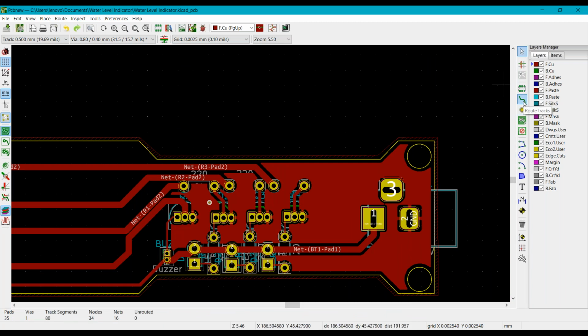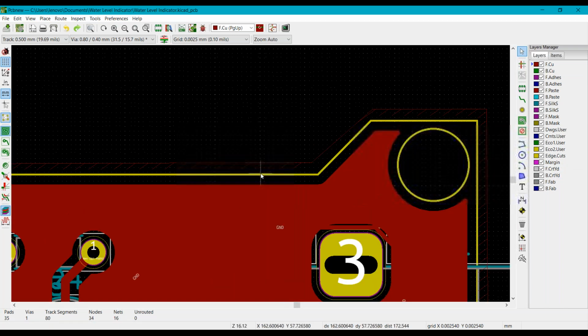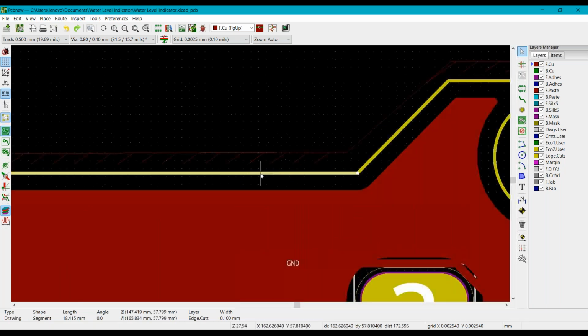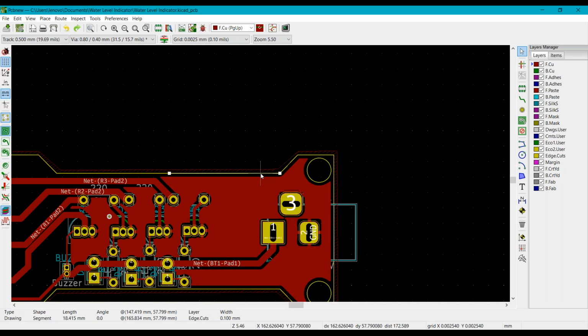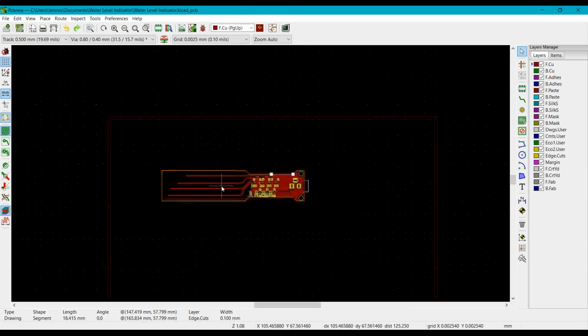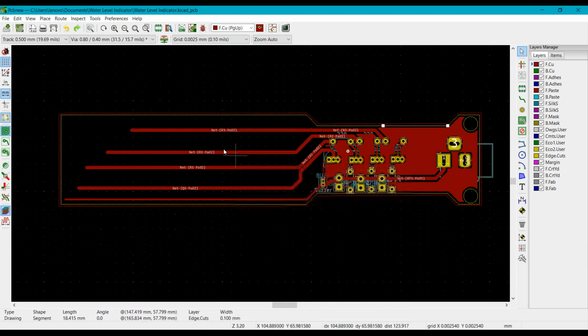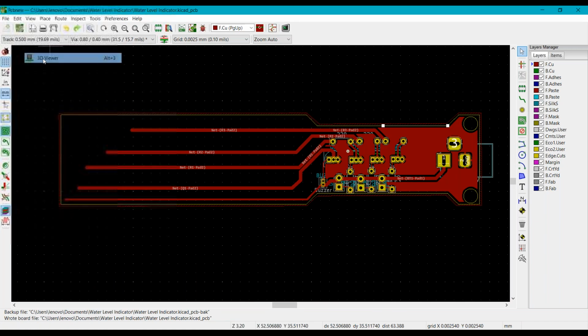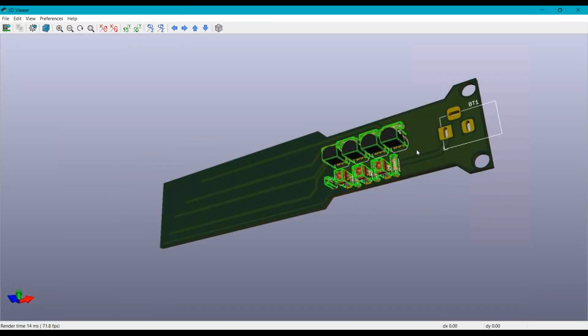And this is the routing tracks. If you want to make connections or tracks, then you will choose this line. F.Cu is your front copper layer, and this is your back copper layer or bottom copper layer. The edge cuts is the only layer with the help of which I made this boundary, or you can say the board layout, which I had done yesterday. So yeah, this PCB is done. Now, if you want to ask any question, then you can ask.